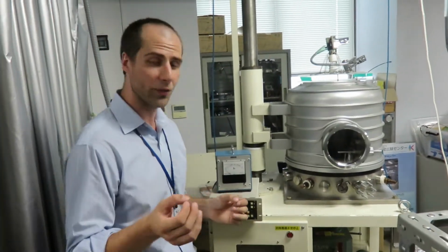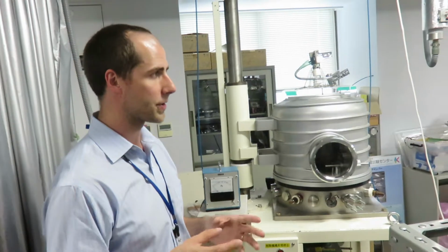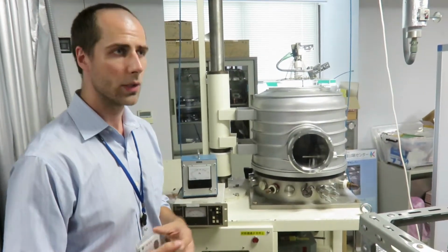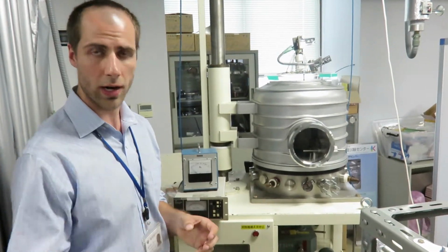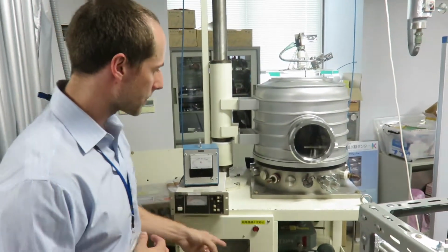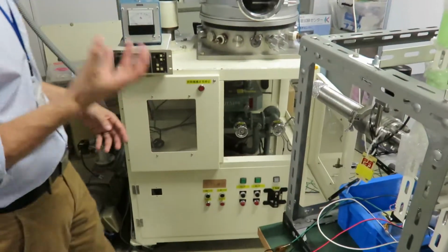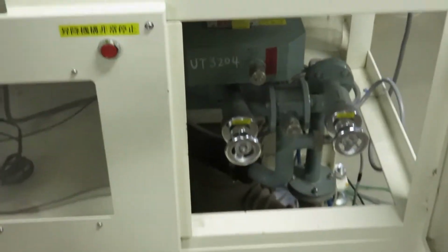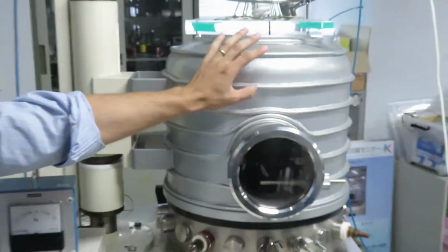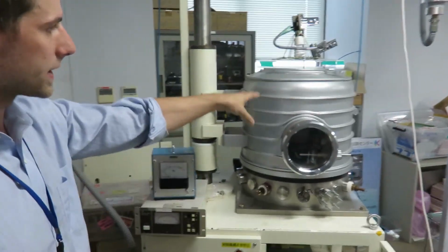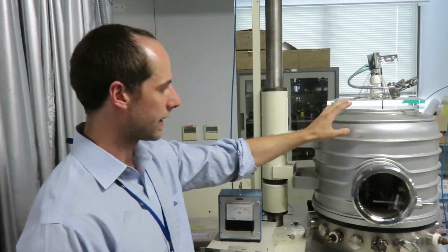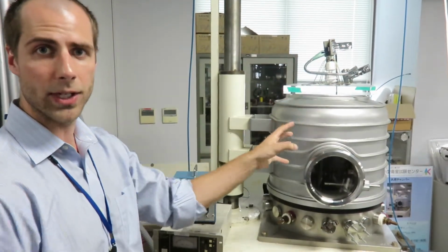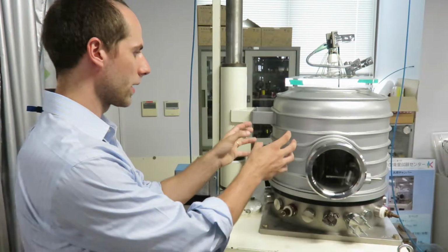If you've been paying close attention, you'll have noticed that for the most part so far we've used turbomolecular pumps for the ultimate vacuum for our primary chambers. This chamber actually uses a diffusion pump. So we use hot oil vapor to capture air molecules inside the chamber to reach our simulated vacuum, our simulated space environment. This is important because we can, in some ways, contaminate the interior of this chamber and not risk damaging our pumps and our chamber.